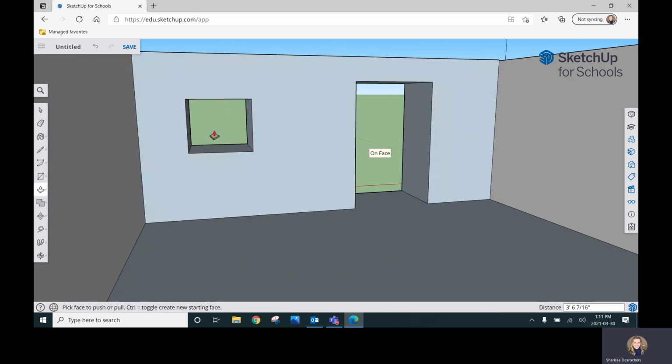If you want to scale things to fit and measure, like I told you before, there's the measure tool that you can use and it'll tell you right there what your measurement is. Here it's approximately 20 inches, or you can use the dimension tool as well. It shows you 2 feet, 11 inches, if you want that information there. That's really helpful if you're trying to put in a window or something.